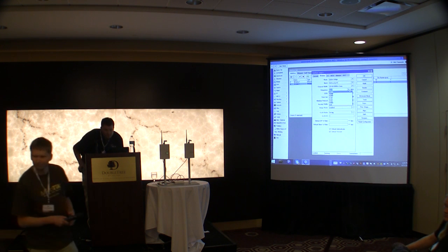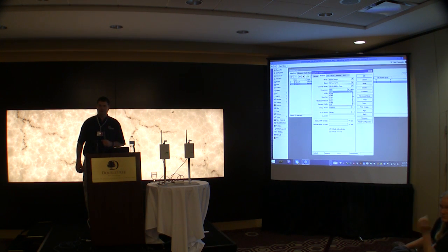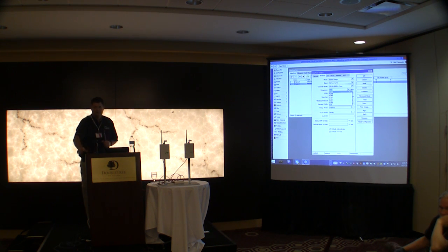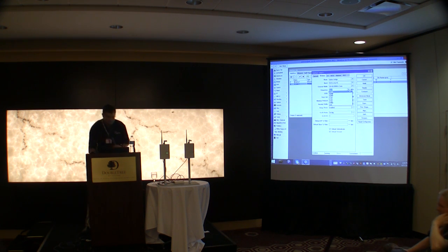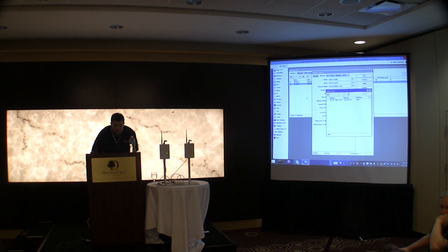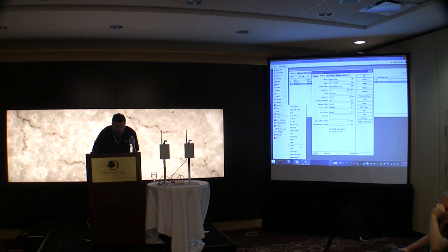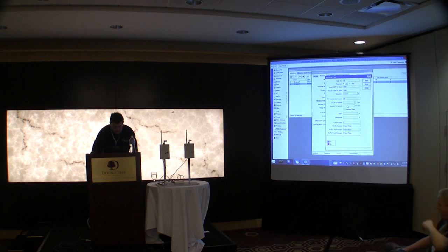I just was going to comment on his comments about GPS synchronization. I know we have several different sites with not MikroTik equipment, with Ubiquiti equipment, back to back. As long as you have good enough RF isolation, you really don't even have to worry about it. Because I have equipment that's maybe 8 inches apart, and I can run the same frequency and still maintain the signal to noise ratio as well as a noise floor of 103 on the one that we just did, and still use the same frequency back to back, as long as you've got proper RF isolation between the antennas. So it just comes down to proper engineering.